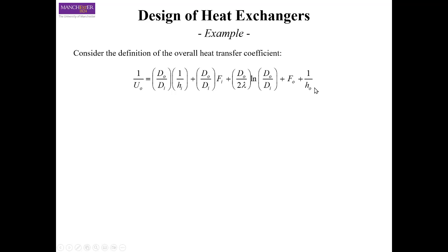Okay. And from the data that is given to us, we know that we have the value of HI. So the heat transfer coefficient due to condensing steam, HI, is given to us, but at the same time, actually the effect of convective transfer inside the tube and the fouling resistance are given together to us.